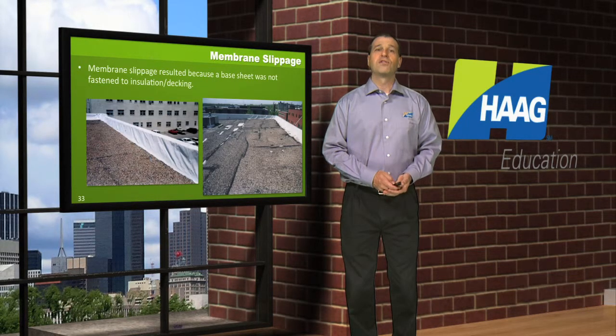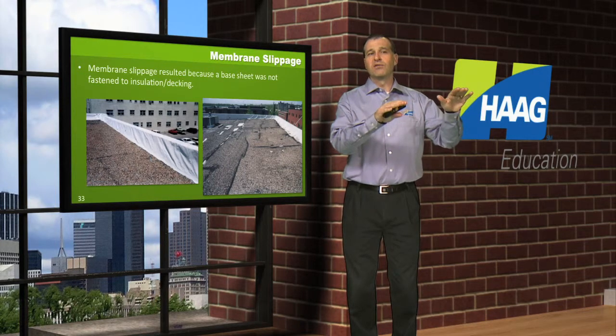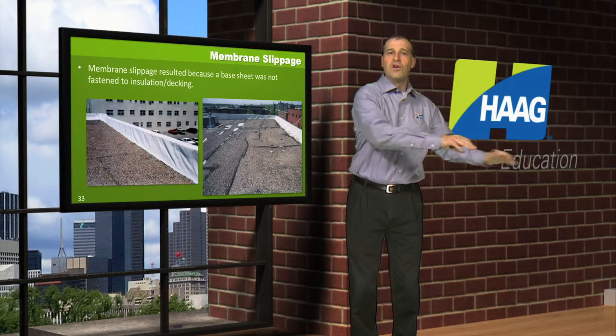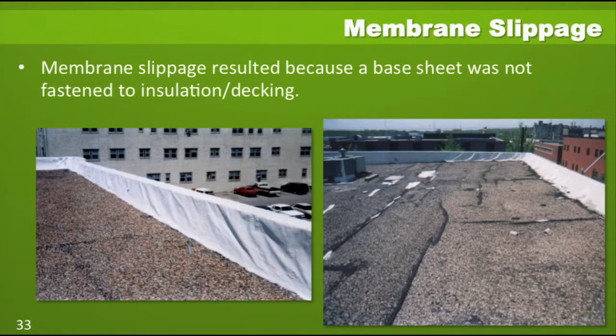When a built-up roof has slope to it, and the steep or special steep asphalt is not used, you can have situations where the roof actually starts to move or slide downhill. One indication of this is shown in the photograph on the left, where you've got parallel diagonal wrinkles in the base flashing on the parapet wall. The photograph on the right shows actual splits and wrinkles that have formed in the built-up roofing as it's pulled away from the upslope wall on the right.